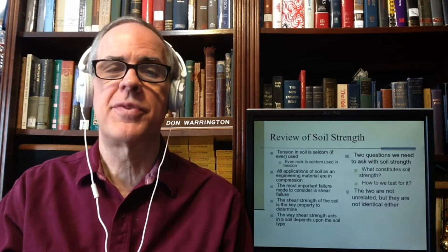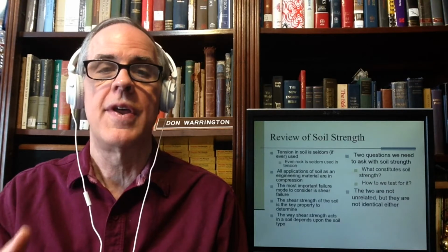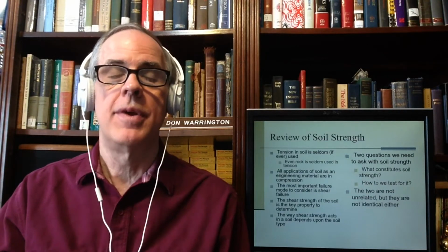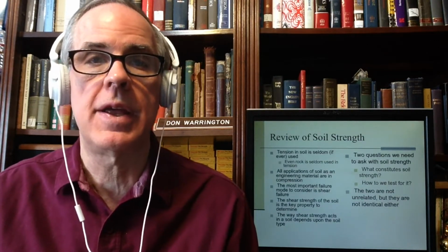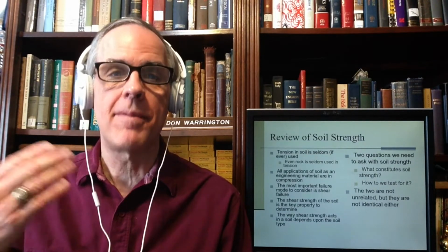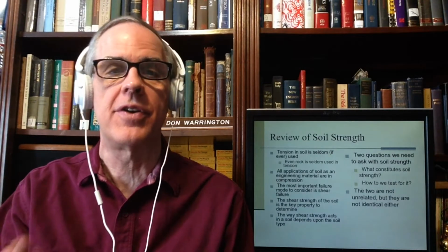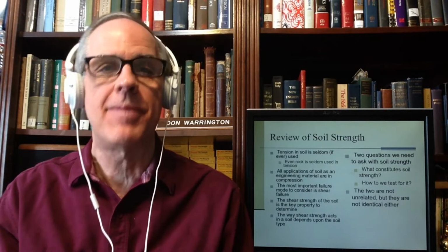The only difference between Tresca theory, and we actually use Tresca theory in soil mechanics in certain soils, and Mohr-Coulomb is the fact that Mohr-Coulomb adds the effect of the internal friction of the soil. Otherwise, they're the same. So Mohr-Coulomb is a maximum shear strength theory of failure, even though it is not the maximum shear strength theory of failure.